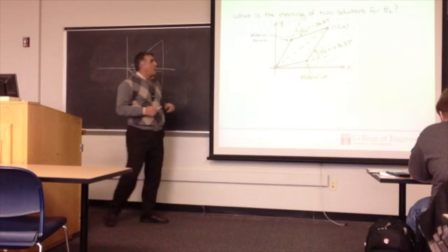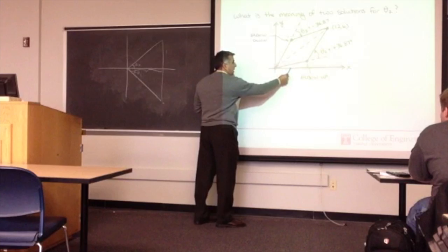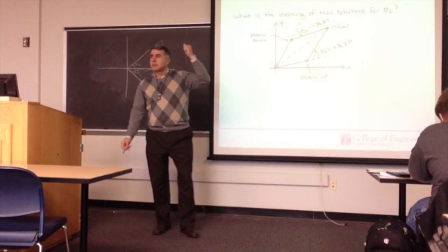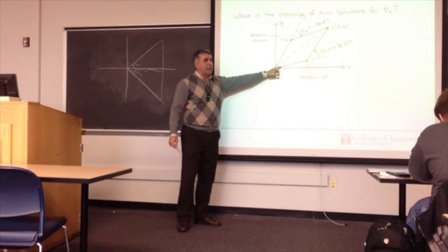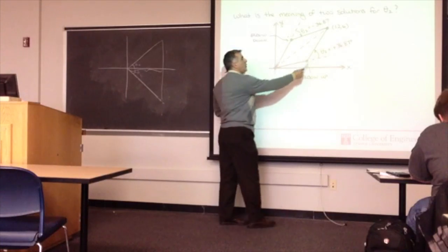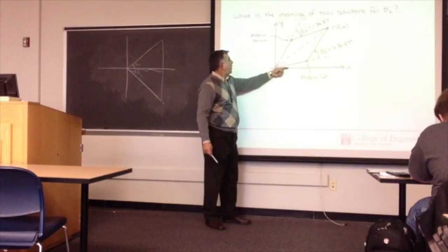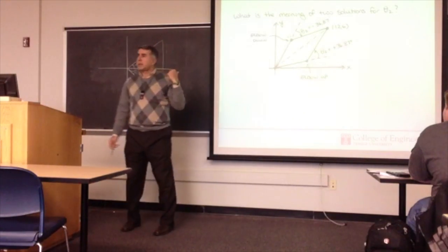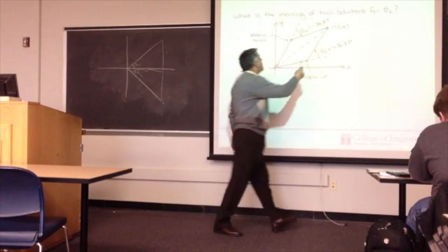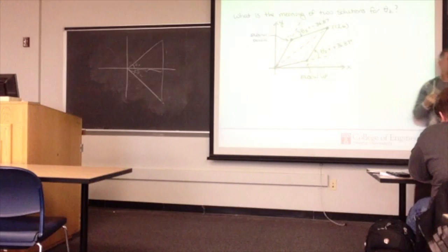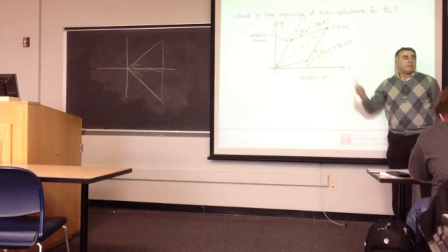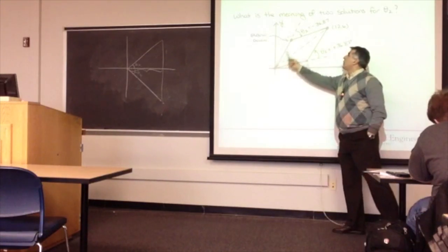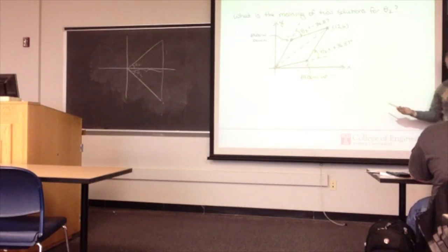All right? So if your theta 1 is this, then we call this elbow up. Okay? We don't know what theta 1 is yet. That is why you get two answers. Because if your theta 1 is this one, then you need to go elbow down. Both of these two will get you to the point. The only difference is, in the first one, the motor has to move in the positive direction, and in the second one, the motor needs to move in the negative direction.